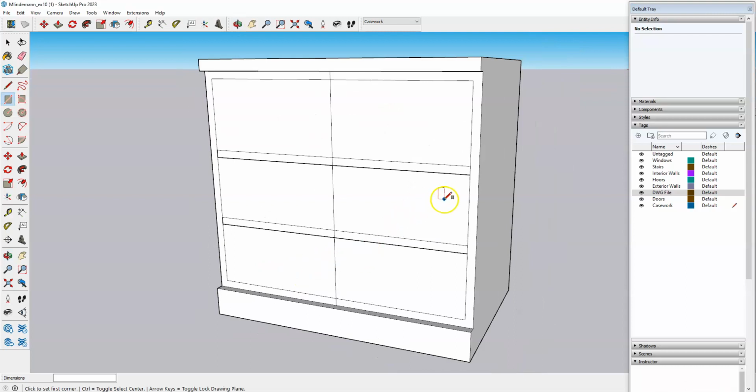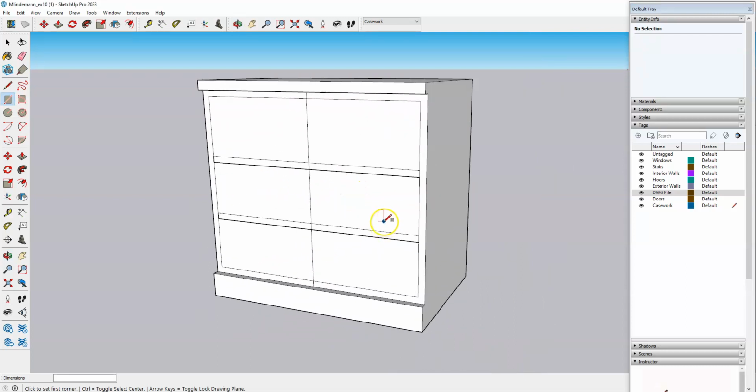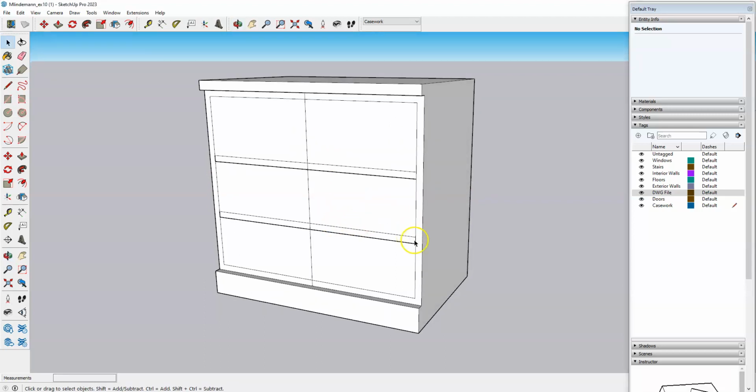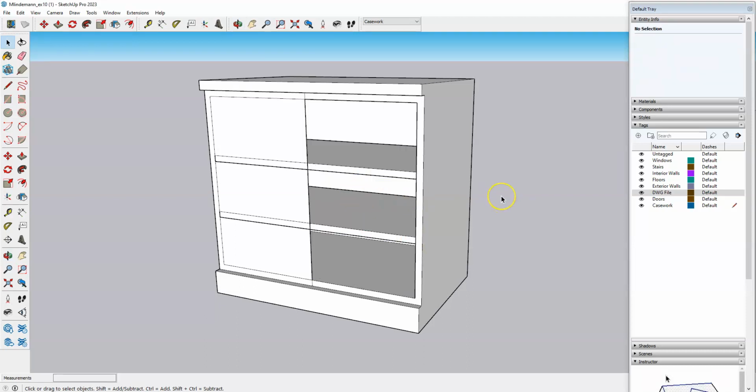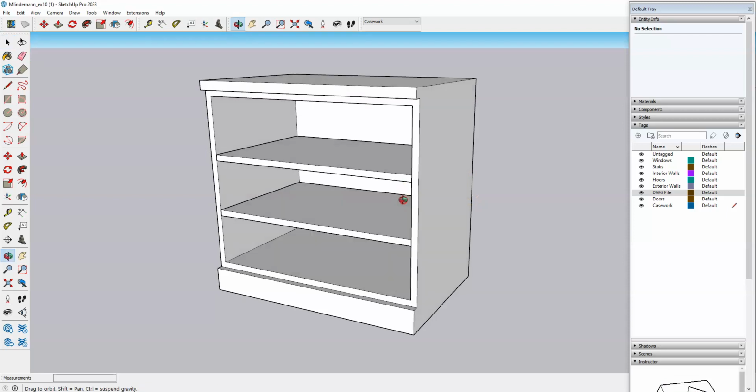And you'll see that SketchUp kind of closed both of them. That's because we don't have everything else in a group. So all of these lines, SketchUp is still recognizing them as lines. So it said, hey, you've created 4 bounding lines. I can now close this as a surface. So if that happened, you can either just get rid of that surface by clicking it and hitting delete, or if you'd like to avoid this in the first place, I just did Control-Z to undo.